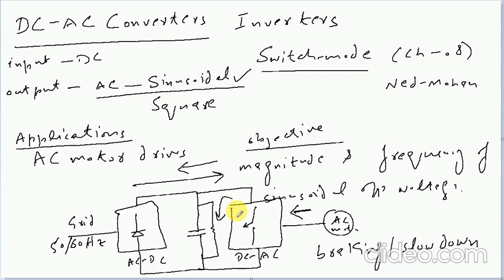But let us imagine that this scenario happens quite frequently: the motor achieves a certain speed, attains some momentum and the inertia associated with it, and then, for whatever reason, quite frequently this braking or slowing down takes place, and after every brief interval reverse power flow starts to take place.